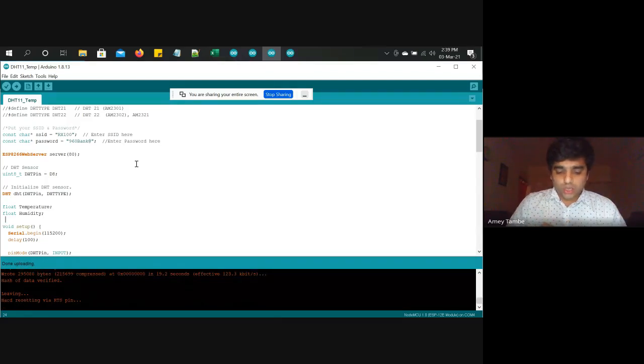So if your connections are in place, maybe at that time also it is not getting connected to the board. So maybe that was the issue with my first NodeMCU. I forgot to mention that troubleshooting point. So this is a quick troubleshooting. I've removed my DHT11 sensor, so everything went well.